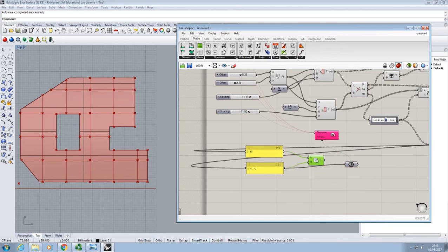And that would mean that as our number of columns was decreasing, our score would go down, and also as our spacing between columns was increasing, our score would be going down. So we could then minimize that combined score in order to come up with a solution that respected both of those criteria. So you can come up with quite complicated fitness functions built up from several different criteria.